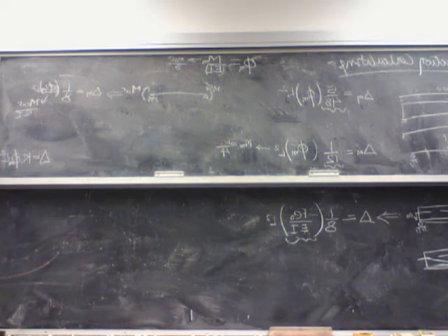So it's a straight line, it has a kink, straight line goes back to 0. So we also have learned that what is the equivalent load corresponding to this draped tendon? It's a point load at the location of the kink, right? So this is similar to a case which has a point load acting at the midspan. Let's call this P equivalent.